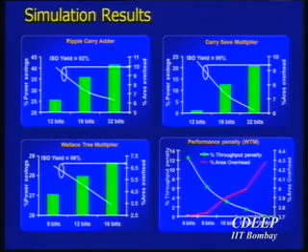A few other examples, going back to carry save adders and so on. Again, this was applied to carry save multipliers, Wallace tree multipliers, and that shows the ripple carry adder. But in most cases, what is really important to see is that it's possible to get a large improvement. The improvement really comes from the fact that I'm scaling my supply voltage down a little bit. That gives me a square improvement, but I'm not scaling my frequency down. So I do get a performance penalty, but it's not going to be too much because I have to, by design, ensure that the critical path activation is rare.